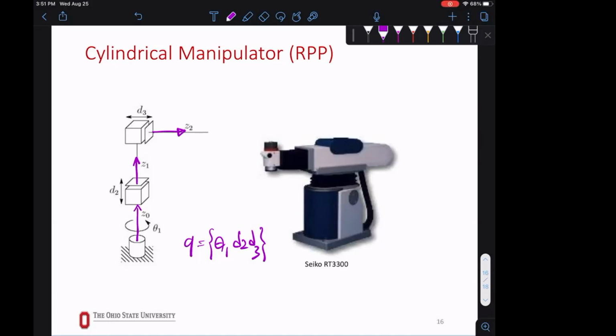Because sometimes there is a distance. So right now, when there is no distance between them, these two are on top of each other. So the question you asked: if you look here, this rotation and translation are one. No, it's the direction of the joint moving, either rotating or translating. Z is just a vector. So Z is the z-axis of your reference frame. So a reference frame is three orthogonal vectors together, right? We just show Z because we know the X and Y. If I tell you where Z is, you can find the other two.